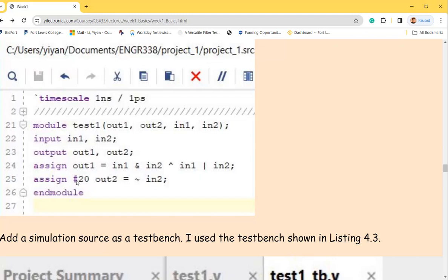Oh, okay. Yeah. So all this is combinational logic for the data flow modeling methods. That's why we need to know the 3 different methods. Right. So the non-blocking and blocking only happens in behavioral, not data flow. So data flow has all the assignments. They are not executed from top to bottom. They are like conventional logic being assigned at the same time. That's how you design the hardware.